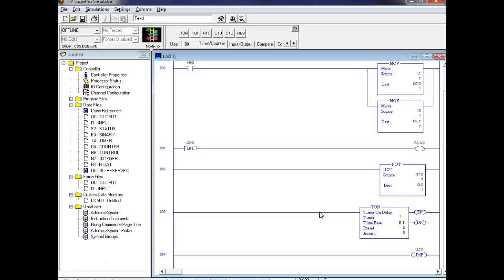Some of y'all have done that in there, where you turn on a light, but then you don't have any type of delay at all. And you say, well, the light's not coming on, right? This has happened more than once. Well, the problem is it's going by so fast. The thing's flashing so fast that you just don't ever see it.